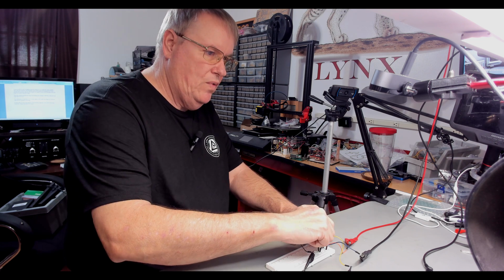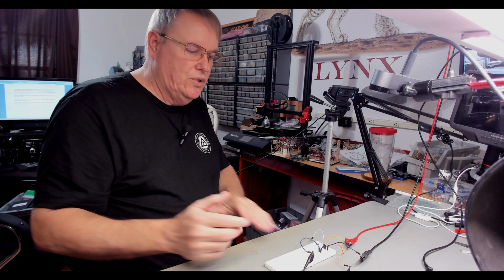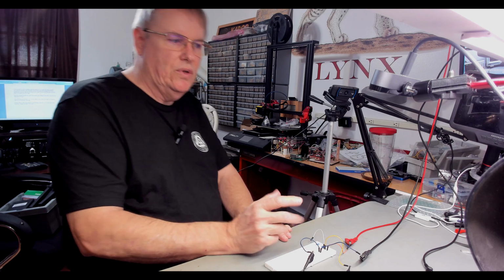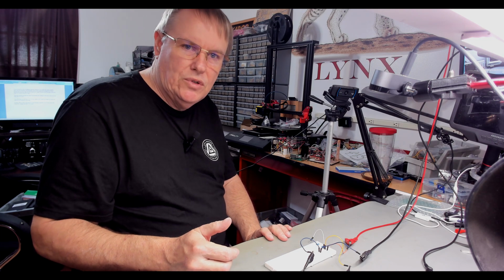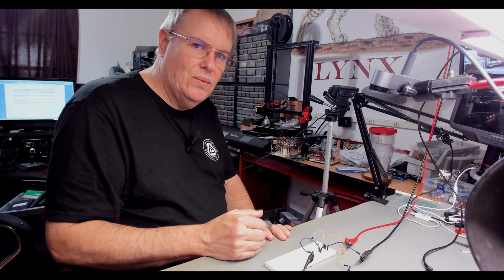Let's go back and prove we do have our 6 volts on this side, but we don't, we're reading like 80 millivolts, but that's just noise on the bench here. But you know, if I go over and hook to ground, I'm still seeing 80 millivolts. That, I think, shows that we're not allowing that DC voltage through. It's a 10 kilo ohm resistor, so it's not hard to do the Ohm's law and show that we should be seeing some voltage across that. If it's blocking the DC, what about AC?